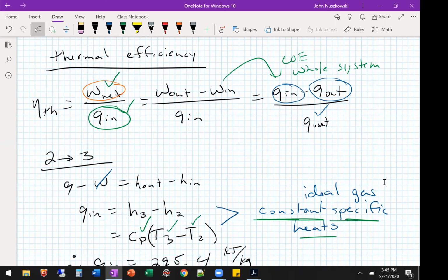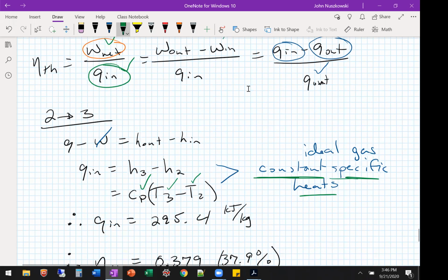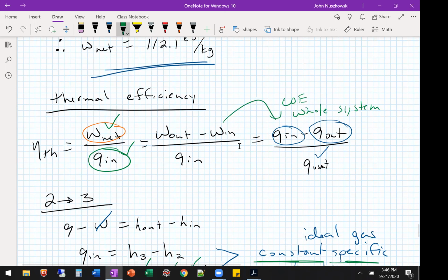Okay. Because in the thermal efficiency, you always need this Q in, so you would need to get the Q in no matter what. Okay. And you can do that with any type of process, or does it have to be constant specific heat? No, this works with any process, no assumptions to solve for this, other than a boundary. And I didn't put in any properties, right? I didn't put in delta H or CP delta T yet in this equation. Okay, where the one that